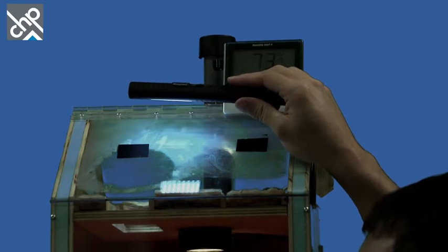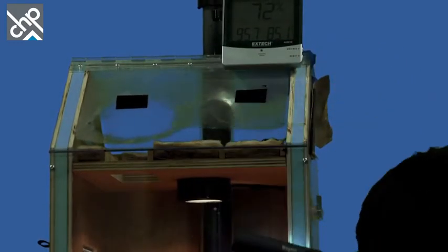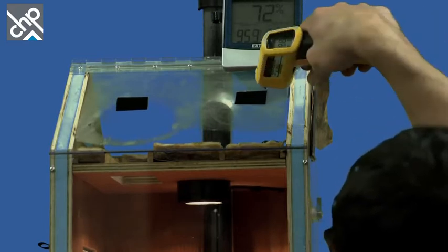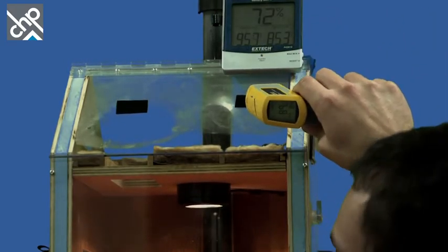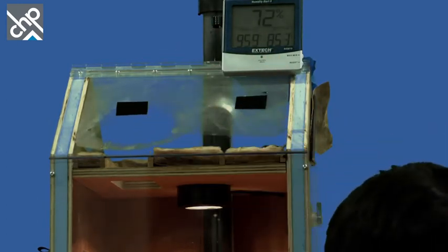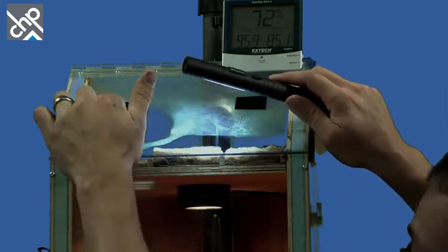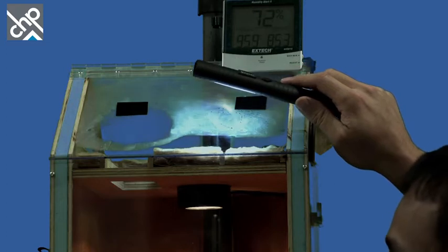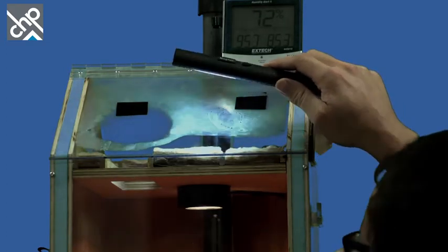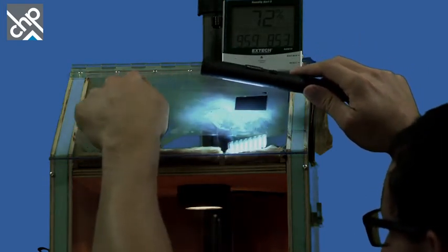Grandma thought she had a roof leak. What do we see going on? So this surface temperature is going to be pretty cool. Let's check it out. It's 89 degrees. Over here it's like 97 degrees, maybe a little warmer. So you're seeing, as that heat was escaping, it was starting to warm the roof deck in this one location. Actually warmed it past the dew point. And now everywhere else that was below the dew point is condensing.